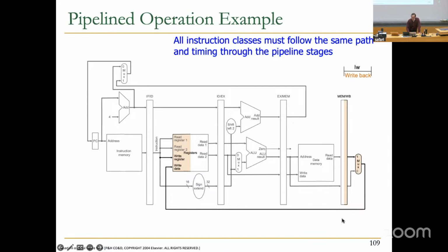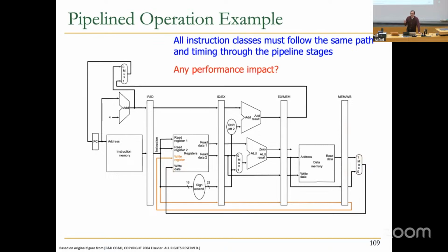You cannot just bypass, because if you bypass, there's a lot of complexity that's added. You could actually bypass in very advanced designs, but not in classical pipelining. So basically, this has a performance impact, meaning an instruction goes through some pipeline stages even though it doesn't need it. It basically consumes some cycles per instruction, essentially. It's very different from the multi-cycle design if you think about it. In the multi-cycle design, an instruction takes as few states in the finite state machine as possible, right? That's the ideal design choice. Here, every instruction takes the same number of stages in the pipeline. But it's not as bad as single cycle, because single cycle is insurmountable as we've discussed.